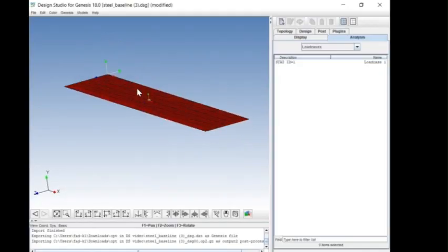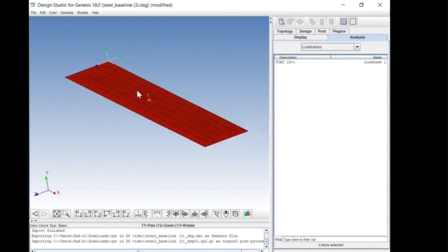So here's our structure. We've got a simply supported structure. It's 150 mil long by 25 mil wide. It's a piece of steel plate. It's 3 millimeters thick. We've got a force of 500 newtons as a UDL, so evenly spread out all the way across the plate. It's set up so that it can rotate freely at both ends. And it can translate at one end.